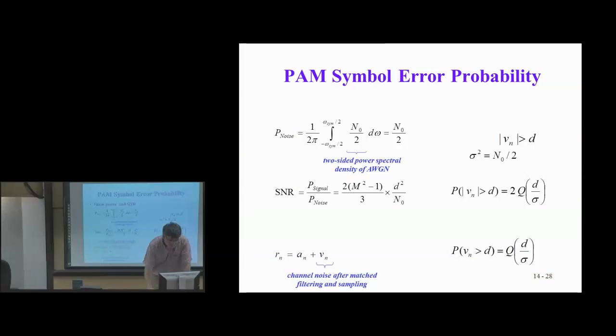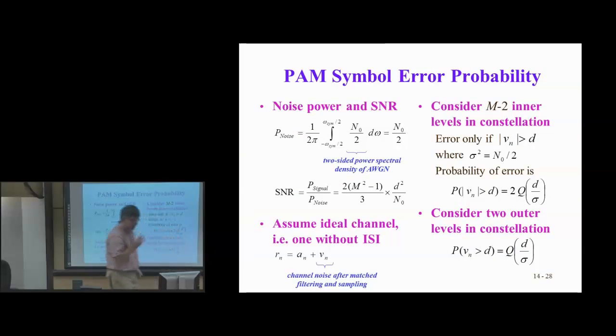All right, so let's go after deriving the SNR in our case. For us, again, we're going to assume that the only impairment is additive noise. So I have my transmission, I have additive noise. This is spectrally flat Gaussian, with 0 mean and variance sigma squared.